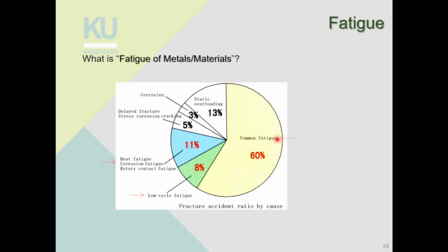It's not a static stress. It's usually cyclic, and that leads to fatigue failure of the component. Because when engineers design something, they think of it as applying a constant stress, and the design concept will try to withstand that constant stress. That means when the stress is not constant, it can cause failure.